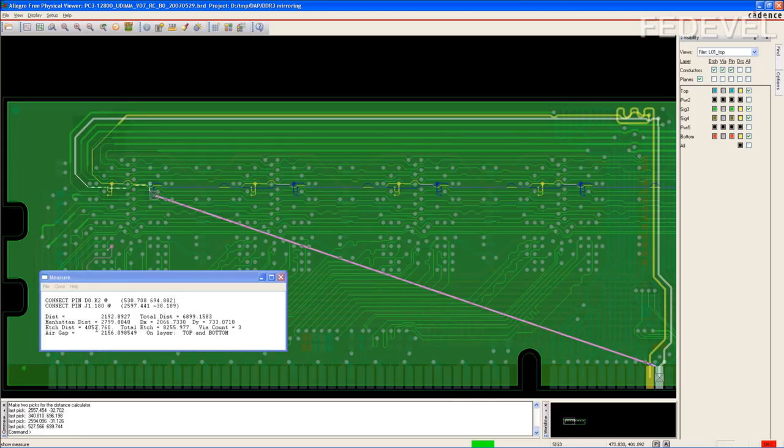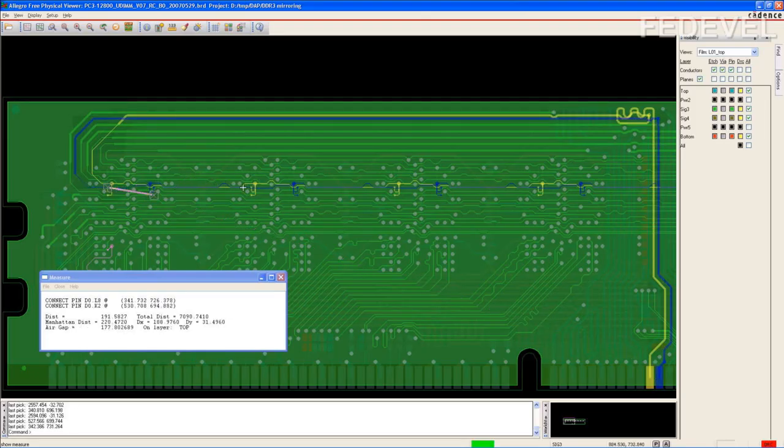So it is in some kind of tolerance, 200 mils. From this pin to these pins which are here. But have a look now. From this memory chip to these memory chips which is here, the distance is 742, and for the blue one it is 742. See? Exactly the same length. So between the memory chips you need to route these tracks, these segments, exactly the same or very similar length.